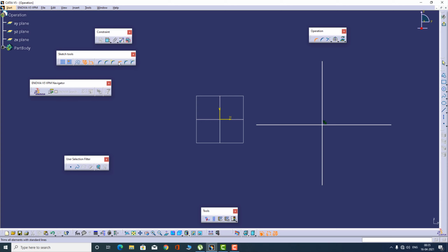Okay, if I select this option, you'll see when I create the corner, that corner is created, but lines beyond the point where the two lines actually intersect will get trimmed. But from the point up till the corner, where the corner meets the line, that line will actually remain the same and it will be a standard line element.